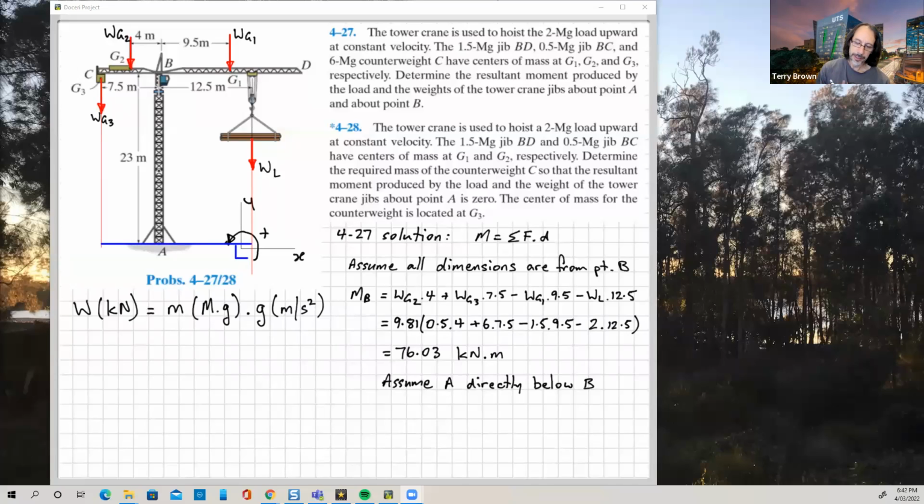A. Right, so here you can see why I had to make an assumption about where A is. Similar to what I was talking about before, up here where we've got this little offset. In the diagram, it looks like A is at the center here, which is where this witness line is, but there's no dot shown for B, and this witness line, as I said, is slightly offset. So again, that's why I say to be careful and deliberate about how you draw your dimensions. Draw them neatly, clearly, and accurately.